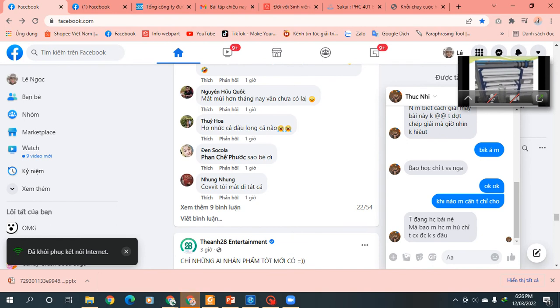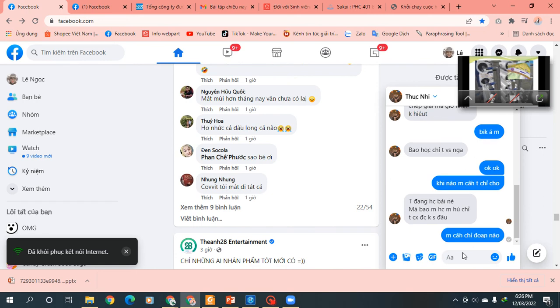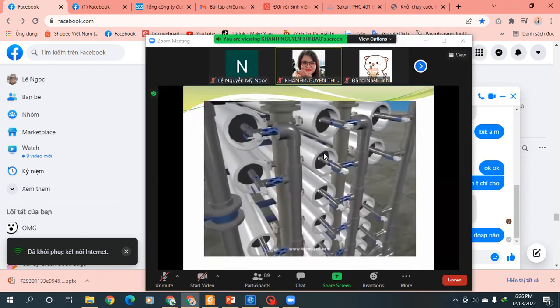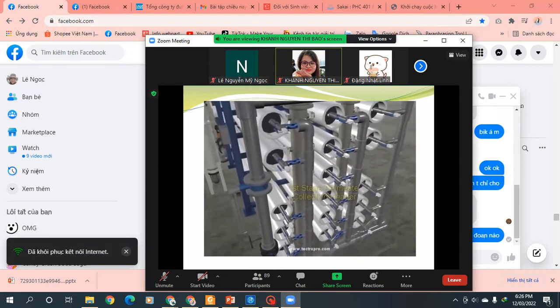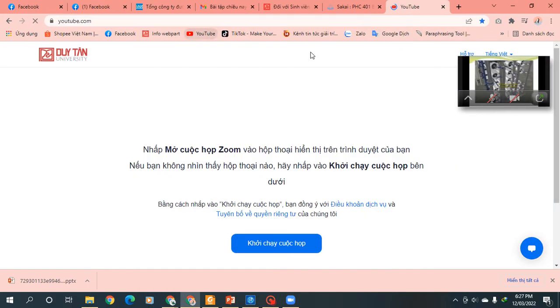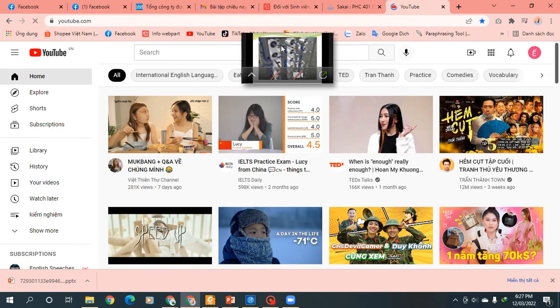As described in the RO Fundamentals section of this course, the first stage pressure vessels have two flow paths which exit the other side of the vessel. Flow which has passed through the RO membrane is collected from a tube located in the center of the pressure vessel. This water is called permeate due to the fact that it has permeated or passed through the membrane. It is also called product water, as it is the purified product water from the pressure vessel. Permeate is collected from all 11 of the pressure vessels in the first stage permeate water collection header.